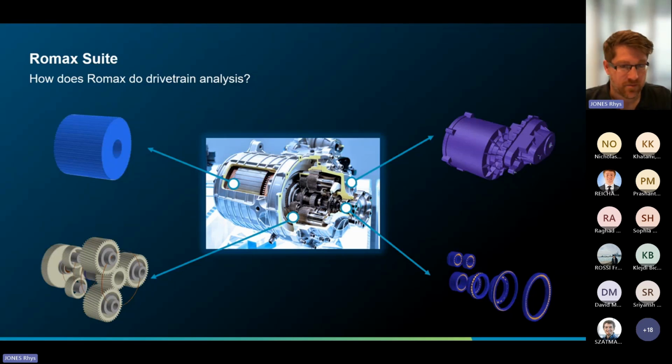So we have very robust formulae for defining the stiffnesses of these components, but is also very, very quick at solving. We also have electric machines that we can include into our model, applying forces and also excitations for NVH analysis.